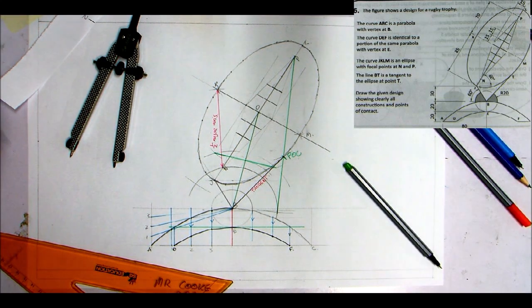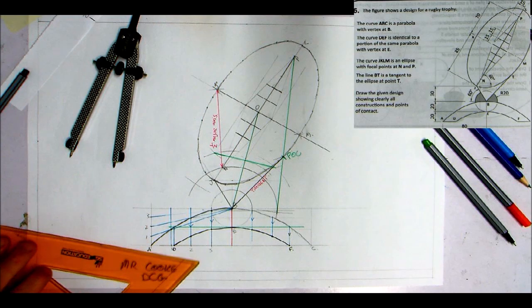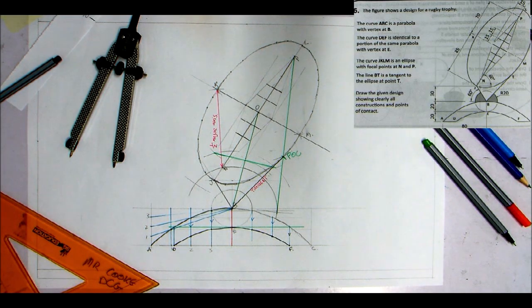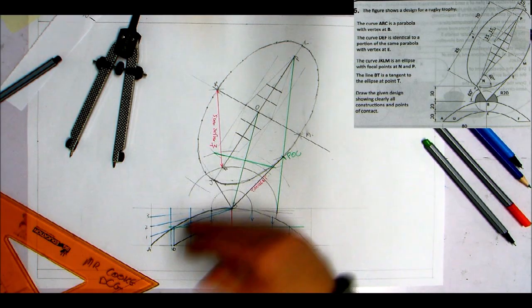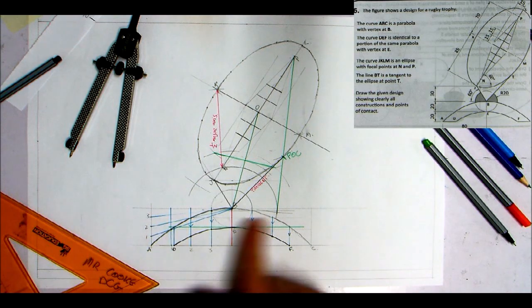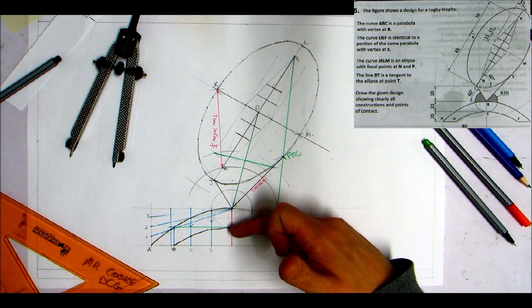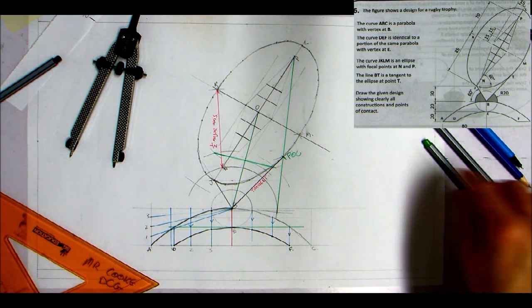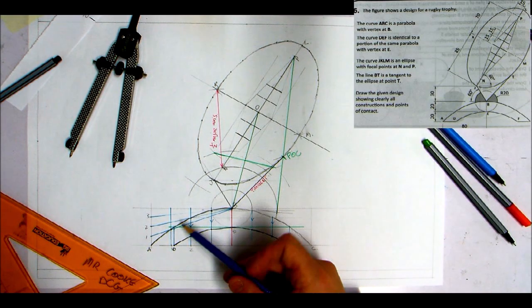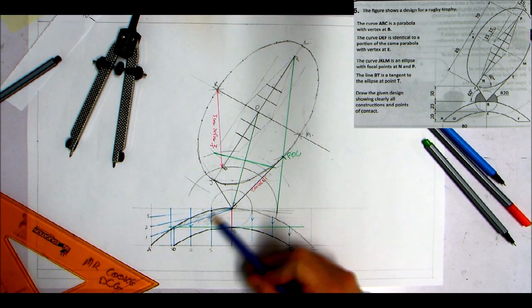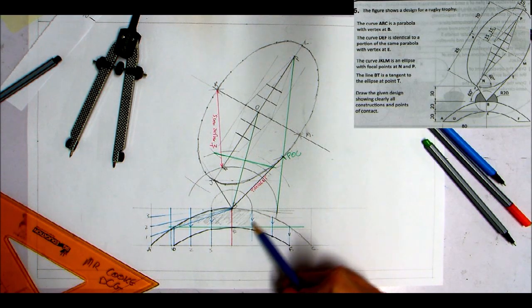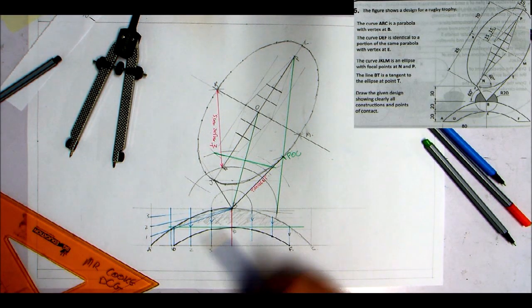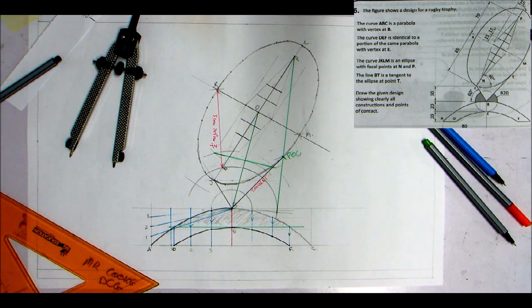Any questions on that? So what's kind of new in that is the copying. It's kind of new, it's not brand new. The copying of DEF, so moving ABC down. It's a portion of it. So what did I do? I stepped down by 20 millimeters because I know that's the height of E. So I stepped down by 20, cut it off, and this section in here, above the green line, that's what I was copying. So I just needed to move all of that shaded section there down by 20 millimeters. Does that make sense? Yeah?